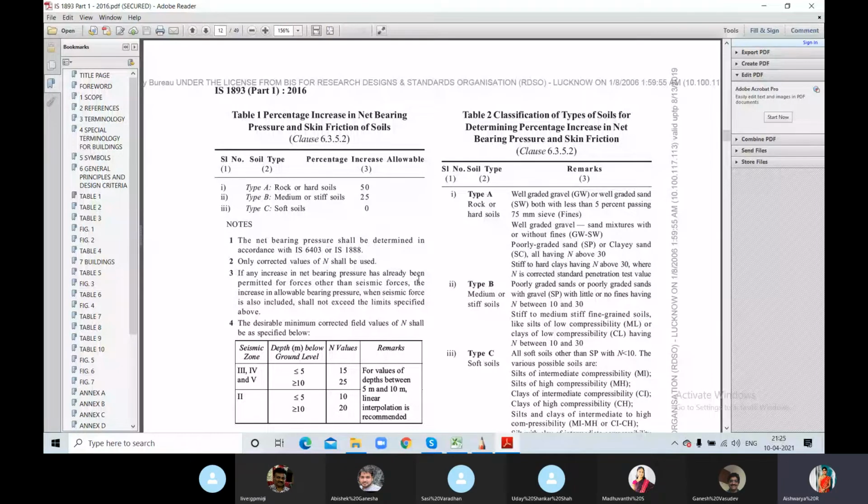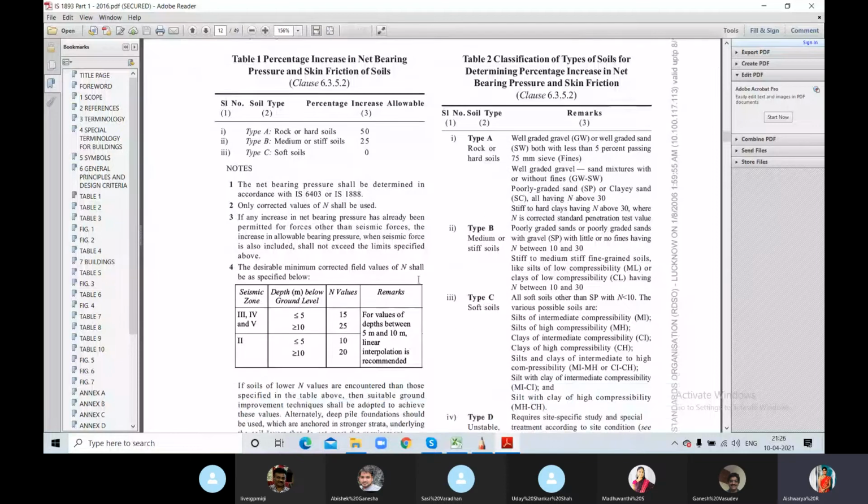Nowadays we see the latest architecture, it involves various shapes and sizes and designing. So while we do that, we have to consider a completely different kind of seismic pressure, and only according to that can we do it. Especially in Dubai and all, you can see the buildings are all of different design, and at the same time they are all very huge tall structures. So they would have considered the seismic activity completely. The design would have been completely different, because they definitely have to consider both wind load and seismic load, even if there's no snow load. So for irregular buildings, we'll be seeing base shear and load distribution.